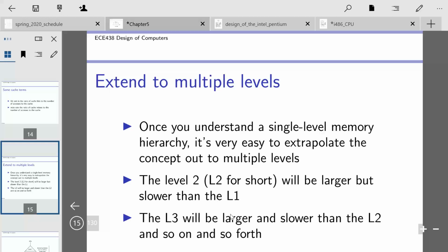When the 486 was published, a lot of the RISC processors actually had off-chip level 1 caches. If you read the 486 paper, they talk about one of the advantages of going with a unified cache versus a split cache: they could fit the entire cache on chip, and that provided significant performance benefits.